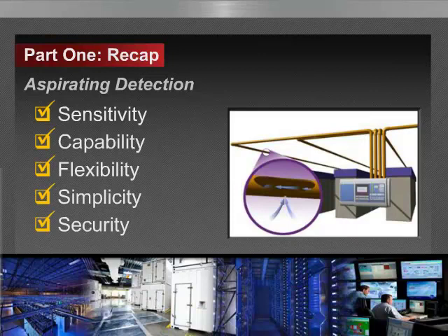Some systems can provide analytic information about the environment. They can be mounted in easily accessible areas. This allows for easy and safe system maintenance when sampling in concealed locations such as below raised floors and underground cable vaults, and will not disrupt operations, and maintenance will not cause security breaches of secure spaces. And of utmost importance, they can provide absolute fixed sensitivity requiring no calibration throughout the duration of their operation. That's just really a recap of, again, those of you that missed part one on air sampling detection technologies.